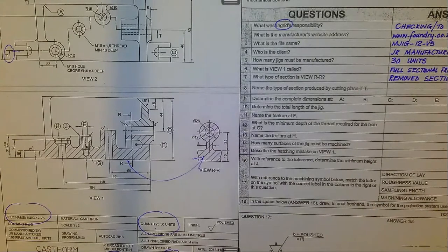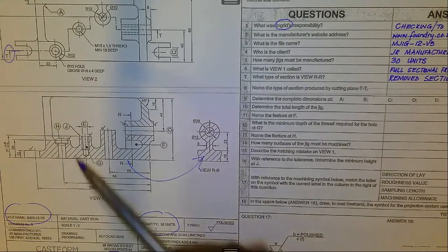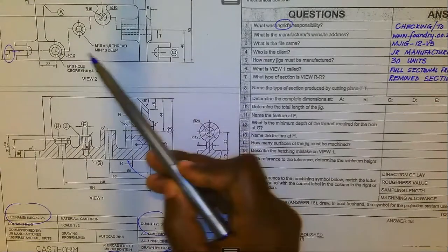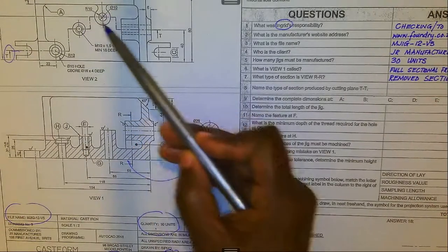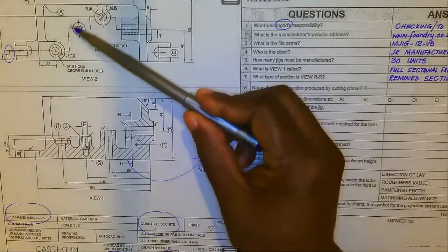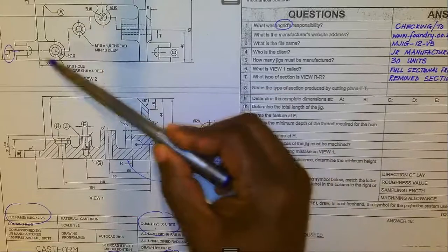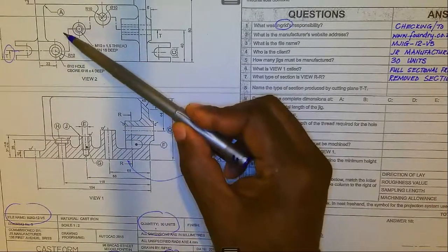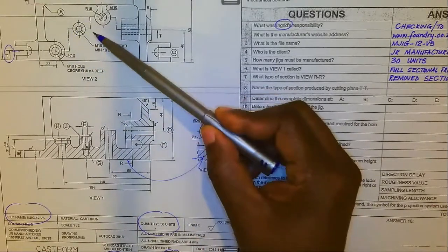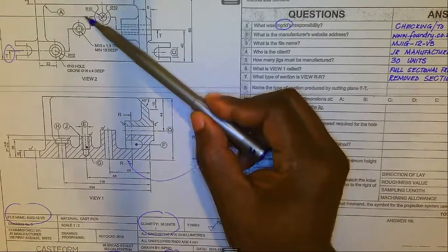It can also be referred to as an offset cutting plane, where you would want to show a section by going through or defining certain details. Remember, if we were to cut like that, we're not going to show this detail, that detail, and so forth. But because you need to show that particular detail, you would stagger it or offset it from its original direction and cut that, then still offset it and cut that like that.